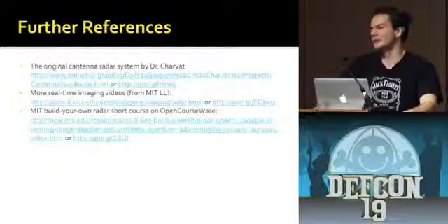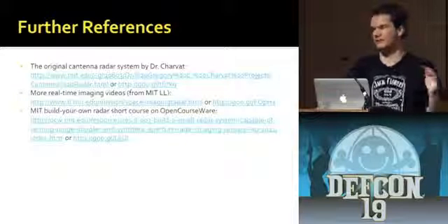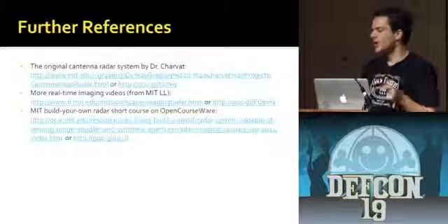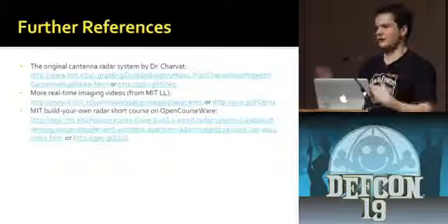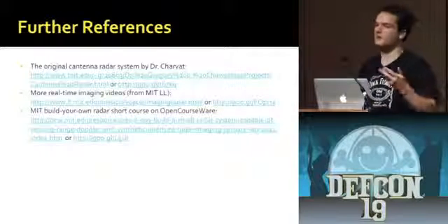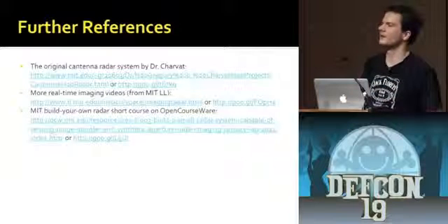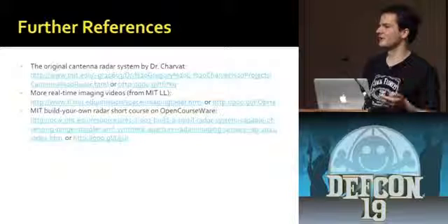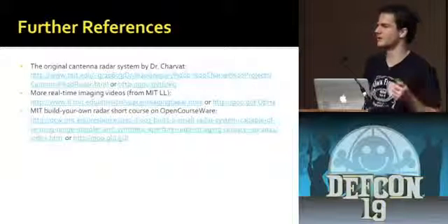On that microcontroller, it'd be pretty hard. The processing power on this thing is pretty weak. It's just useful for quickly grabbing data. If you switch to a DSP or a nice ARM, or an FPGA would probably be the best option in that regard, you could definitely do that. It's not a very computationally intensive process. I mean, this is a Python script I was running to do the FFT.